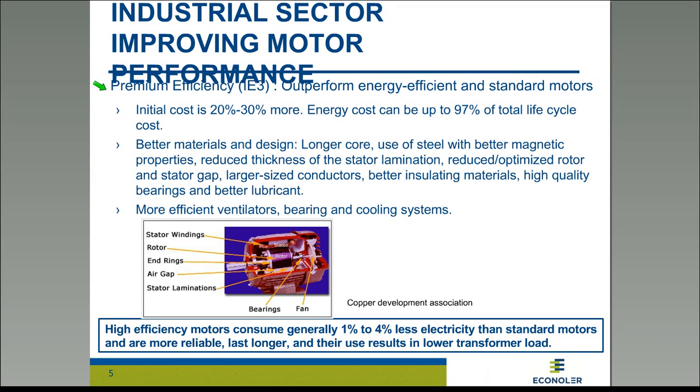There's the energy efficient category, and there's the premium efficiency, which corresponds to IE3 in the European Union. What we can say about high efficiency or premium efficiency motors is their initial cost is slightly higher than standard efficiency motors, and that's because they use more advanced technology, and manufacturing requires more precision and better material. But this first cost is not really so important when we consider the life cycle cost of operating a motor